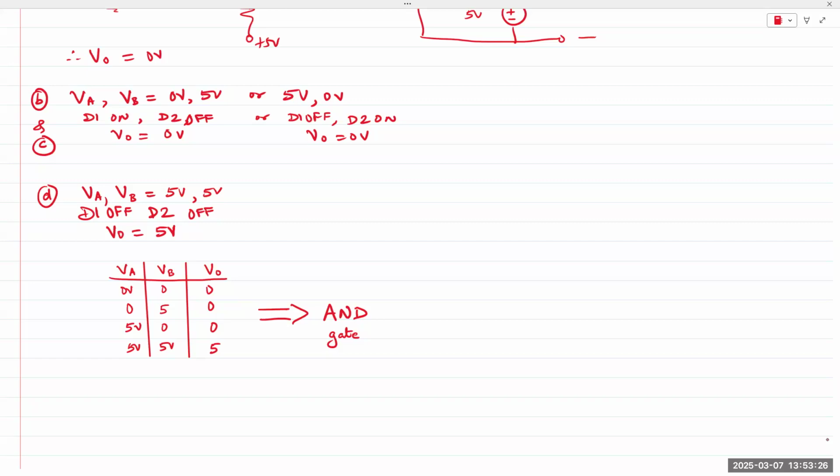That's why in power supplies we have current limits, voltage limits, and built-in circuit protection. So if you're ever working in the lab and there's a short circuit in your procedure, the power supply turns itself off. It's built-in circuit protection.